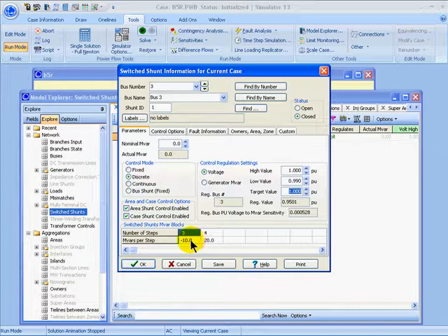I also have 4 blocks of +20, and the device simulator can switch in or out basically any one of these blocks, so you can get any linear combination of the number of steps times the megavar per step when you're in discrete mode. If you're in continuous mode, then the simulator will allow it to produce a nominal megavar that is anywhere between the absolute minimum and the absolute maximum that could be achieved from those blocks. So in this case, the limits for the continuous control would be -30 megavars all the way up to +80 megavars.